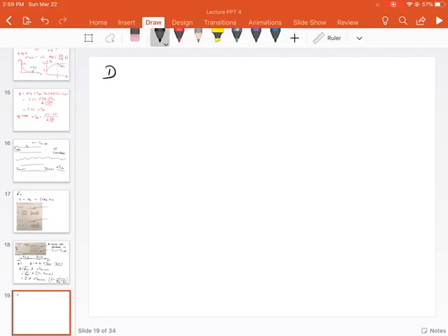First we have to take a guess, and we assume the surface temperature is somewhere in between the hot water and the cold air. So it's really up to what you take. I typically start with the average of the two, let's say the hot water temperature and the air temperature divided by 2. And you don't have to take this, you can take something more reasonable.